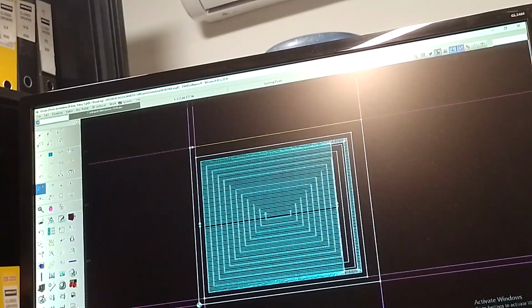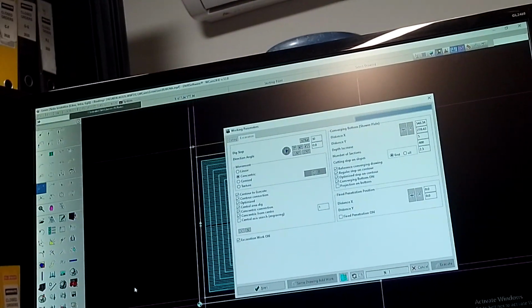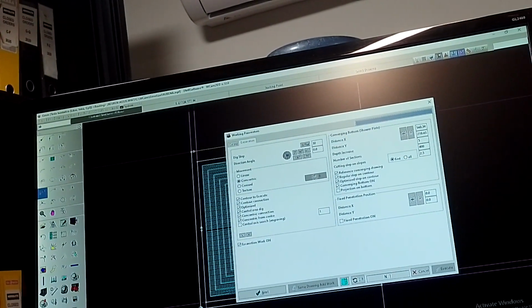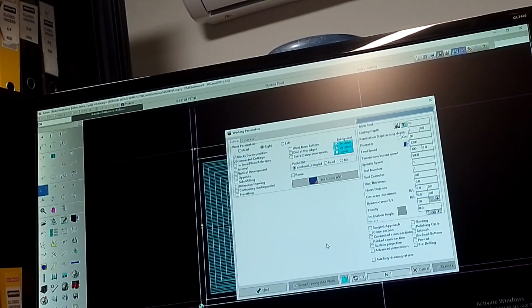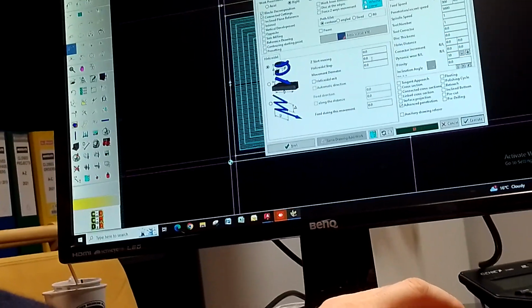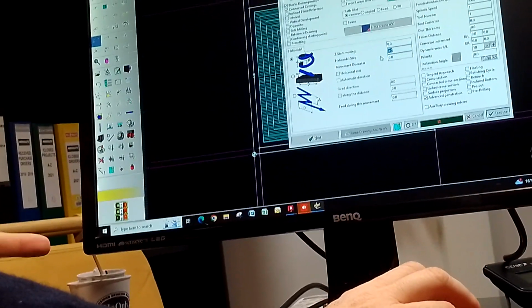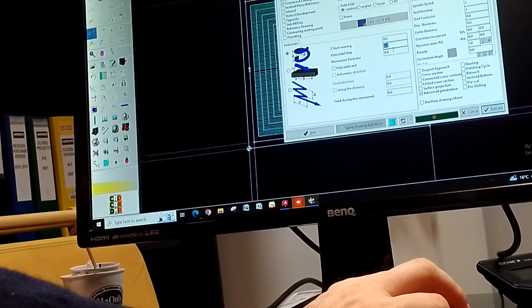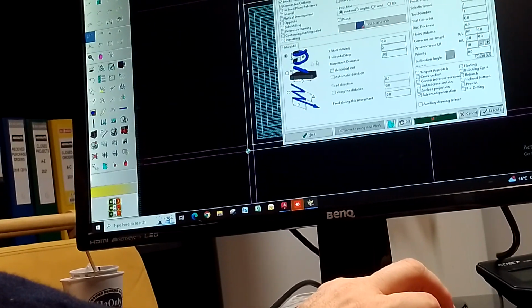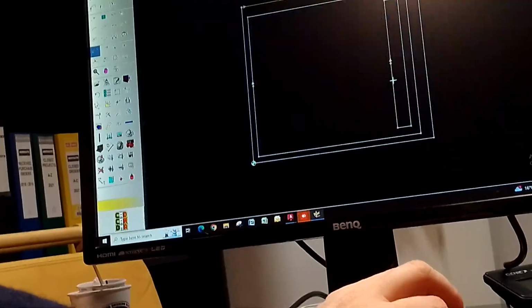And in this case also, it's better to enter in the material with a helicoidal movement, not directly in vertical. To activate this advanced penetration here, you select this one. Here you put the helicoidal step, for example, put 2 millimeter also here. And here again 30 millimeter is the diameter of the helicoidal movement.